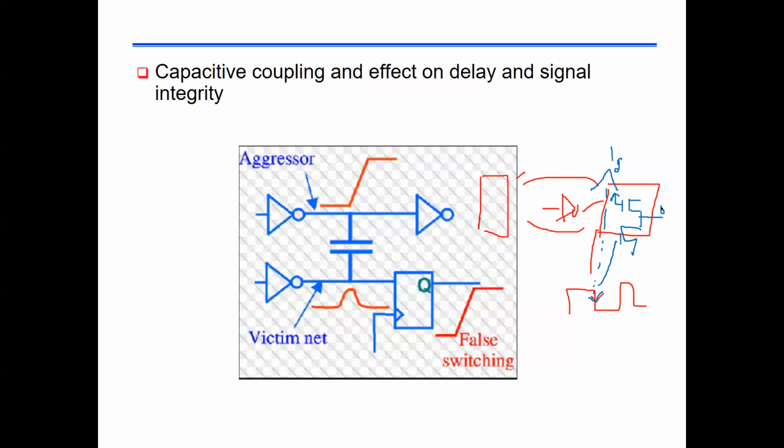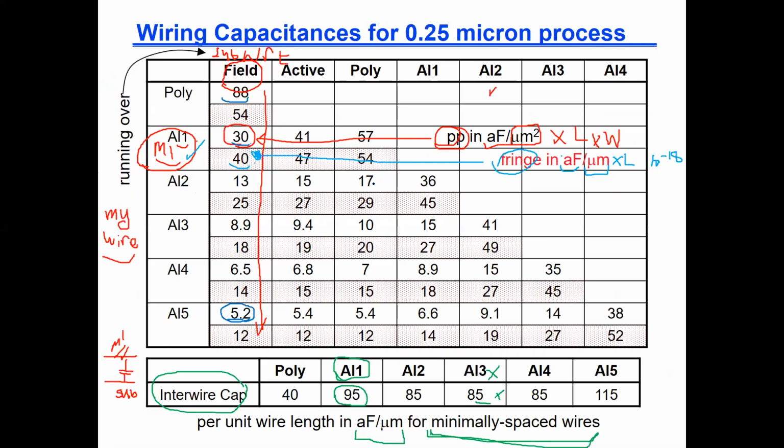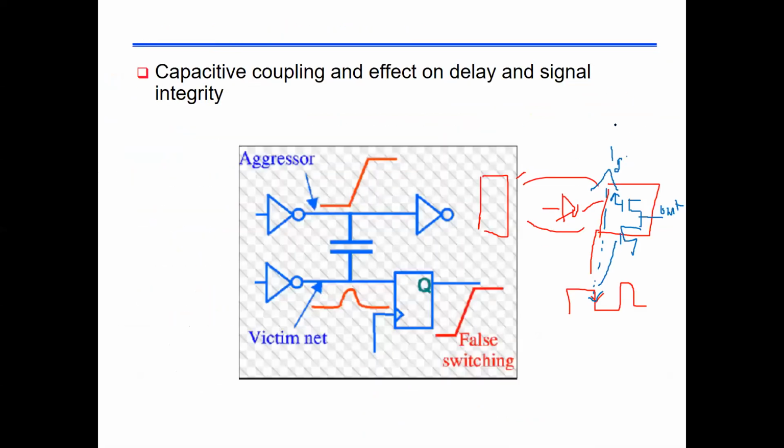So I will see something at the output that I may not have seen if I had not received this noisy signal by mistake. If the noise spike had not come with the falling edge of the clock, we would not have latched the false value. So there are many factors: when the clock comes, how large the noise is, and how much the circuit absorbs the noise. Is this clear? Okay.